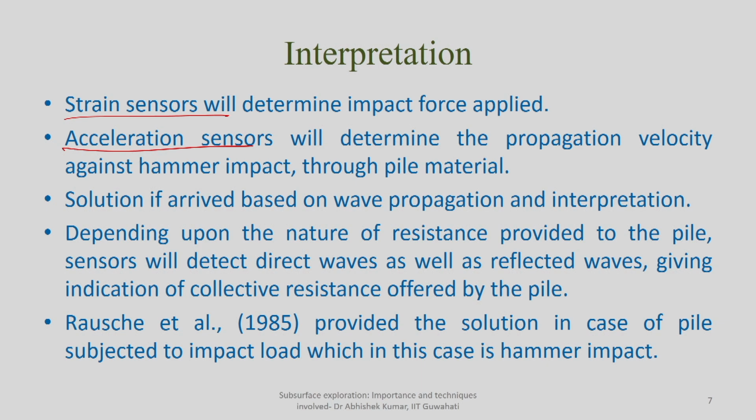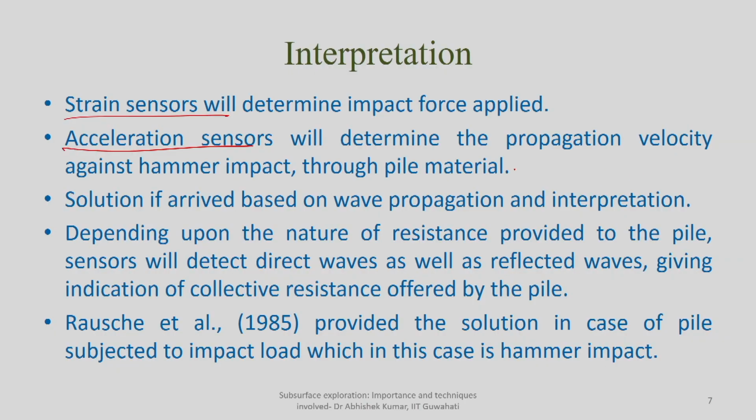So, very clearly, strain sensors will be used to find out the resistance to impact load, and acceleration sensors will be used to find out the response of the pile material, maybe in the form of propagation velocity, particle velocity. This should be the propagation velocity of particles in the pile material against hammer impact.